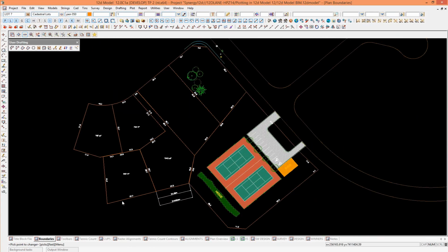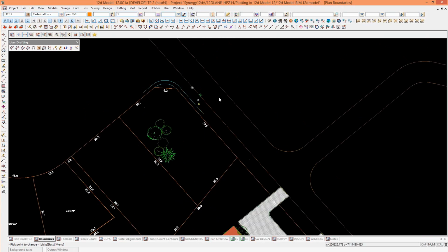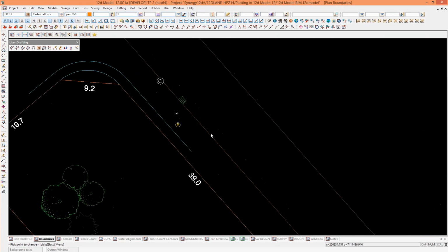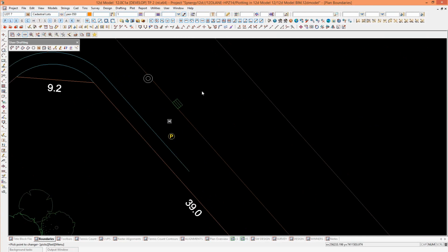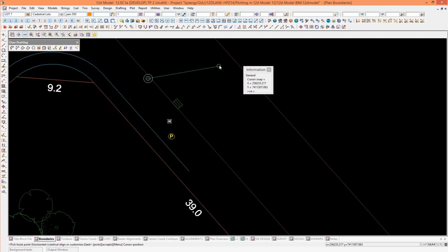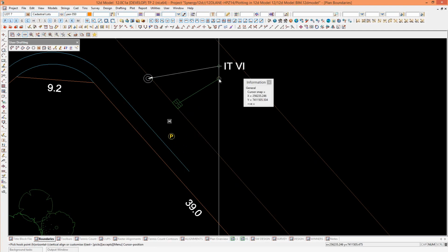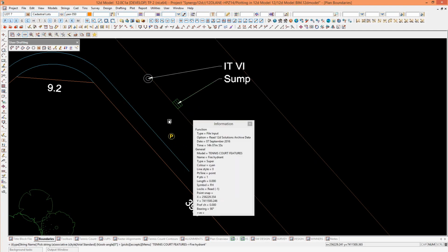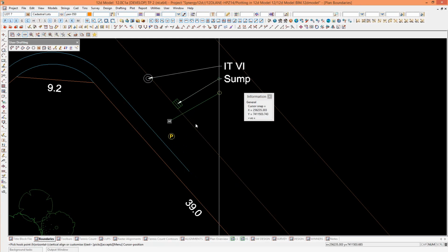We've talked a bit about attributes and names. Our surveyors go out and they actually create or do a good picking up with names and sometimes attributes. Just doing drafting, like you can actually just create leaders and just label things. So I'm just going to create a leader and label some of these features. It's just a quick way of labeling things up. You can see here it's got an auto align, and that's just using the straight out name of the actual string as it was picked up in the field.